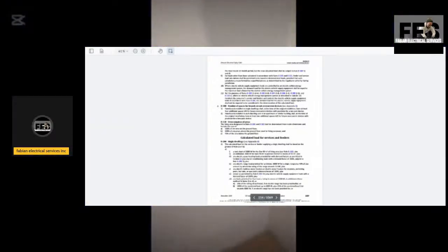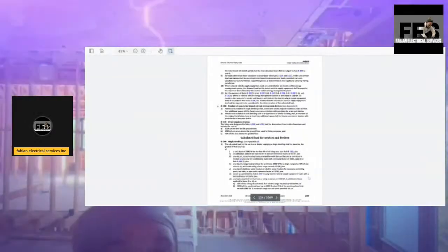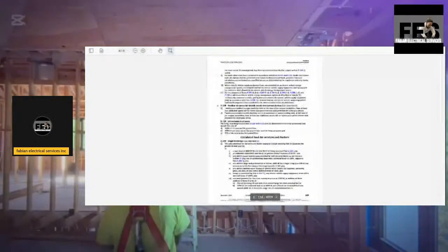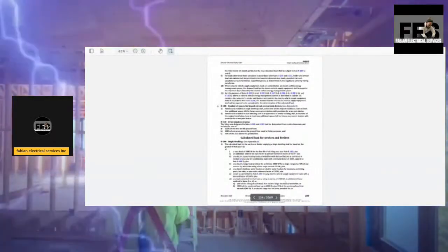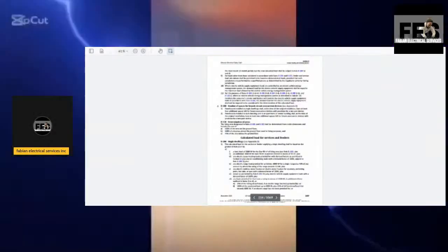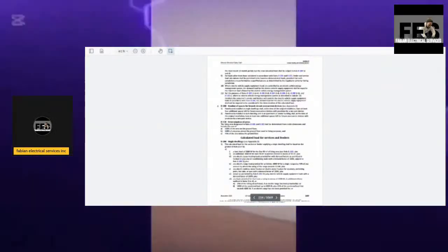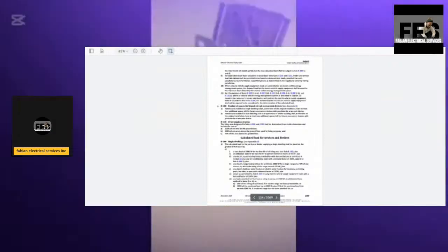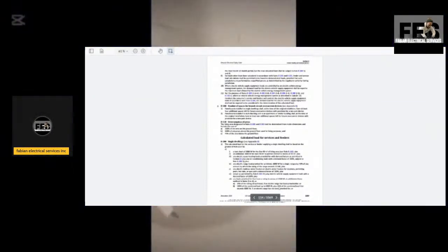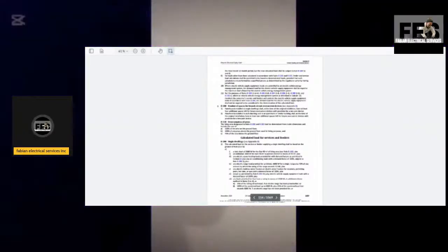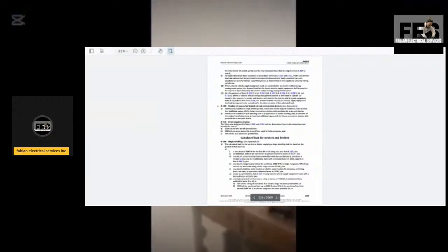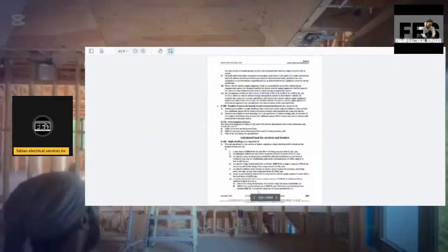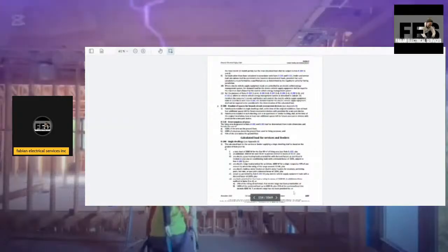Plus, except as permitted by Subrule 8-106 11, any electric vehicle supply equipment loads with a demand factor of 100%, plus any loads provided for that have a rating in excess of 1,500 watts, in addition to those outlined in the items above: 25% of the rating of each load if an electric range has been provided for, or 100% of the combined load up to 6,000 watts, plus 25% of the combined load that exceeds 6,000 watts if an electric range has not been provided for.